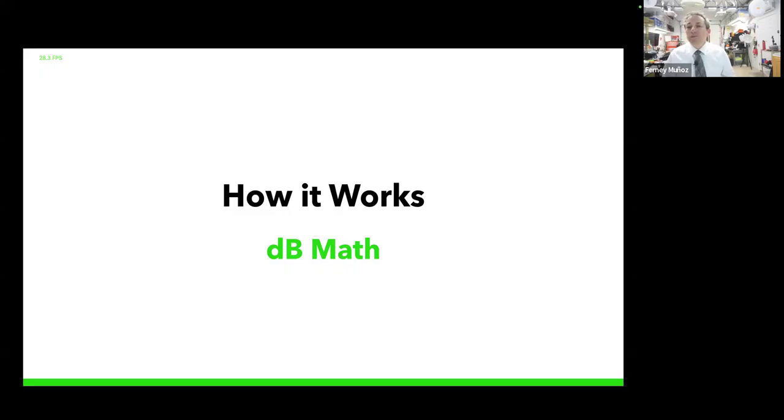We receive documents all the time about power requirements, like, we recommend that our access points are configured at 14 dBm or 17 dBm, and we're talking dBm, not with an I, with an M, and that's relative to a milliwatt.